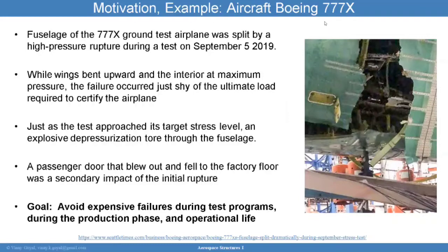And a motivation I want to provide to you in today's lecture is the aircraft Boeing 777X. The fuselage of the 777X ground test airplane was split by a high pressure test. So typically, when you're trying to fly an airplane or a launch vehicle, and you want to deploy that to your customers, typically you have to do a qualification test. A qualification test will take the design and test it to the limits of that structure. And so the high pressure rupture test is one such test.